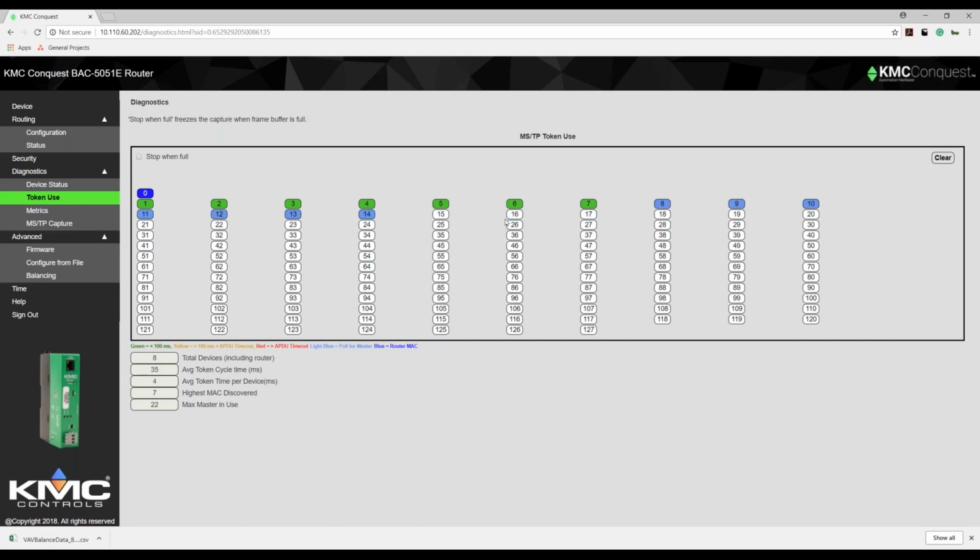The best recommendation, so if you look at the router in my briefcase that I take out, I generally start my networks at 3 and go up from there. That way, if I want to have some other router or a connect node or other BACnet software, I've got 2 MACs on the bottom to always know that I can insert a controller there. But it's whatever your preference is, as long as you're following the rules and being consistent, you shouldn't have any problems.